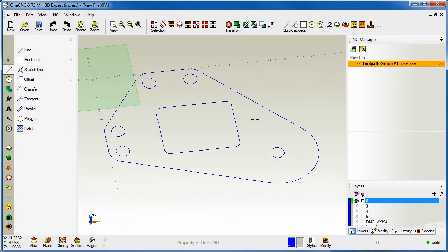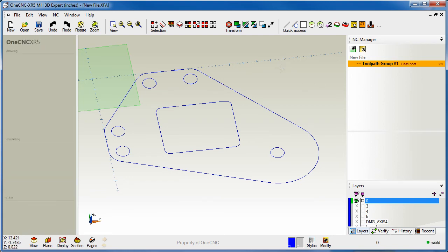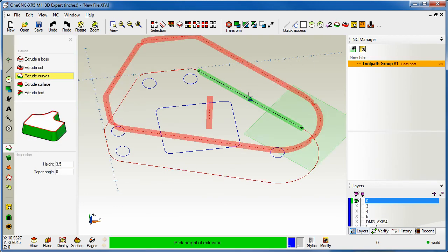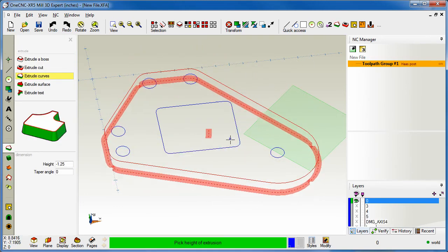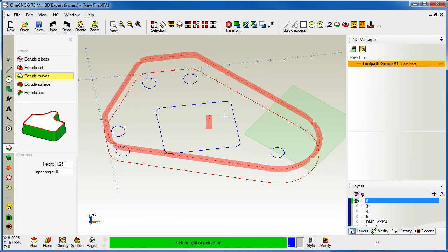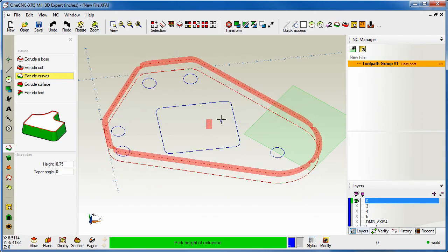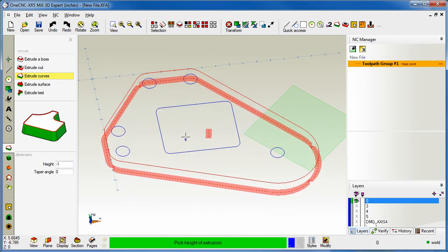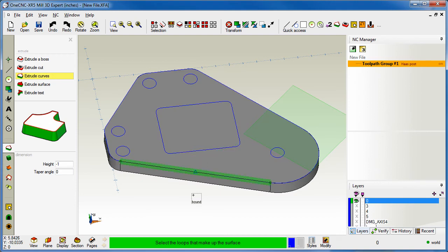Now at this point we can start to apply our manufacturing. But instead I'd like to demonstrate some new features provided by XR5. Let's take a look now at the Extrude tool. I'm going to head up, grab Extrude. Once I grab my boundary, notice now that within XR5 we can extrude dynamically. You can also snap to the same units that are provided when snapping in X and Y. If you look over here for height, I can easily now snap to Z-1, left click, and there's the solid model.